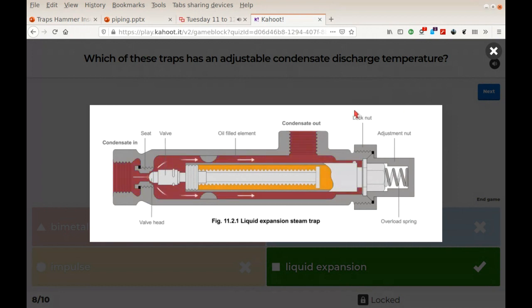When the system is cold, the pressure is relatively low, and then it warms up, the steam pipes warm up, and the steam pressure rises until the steam pipe is all warmed up and we reach a temperature corresponding to the temperature and pressure of the steam. So ones with volatile liquid will follow that pressure curve as the steam pipe heats up.